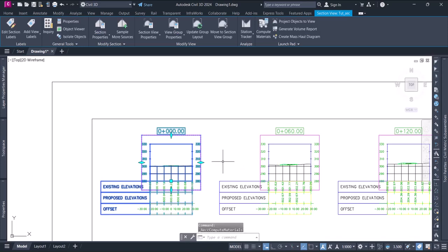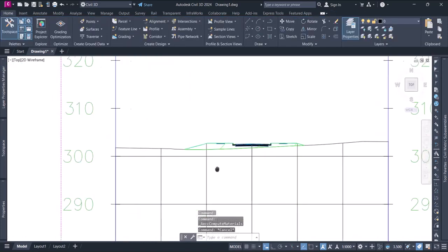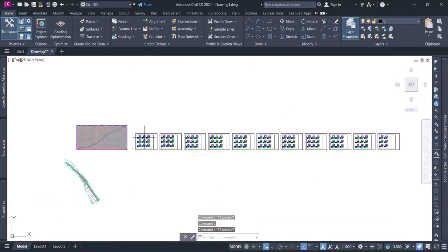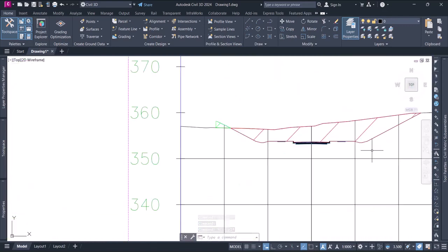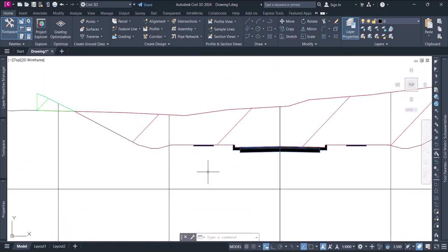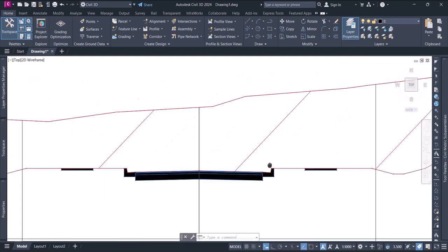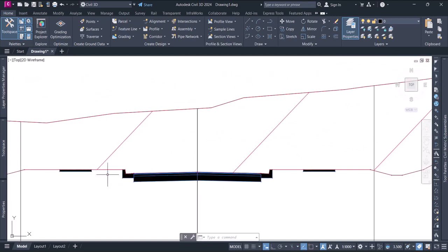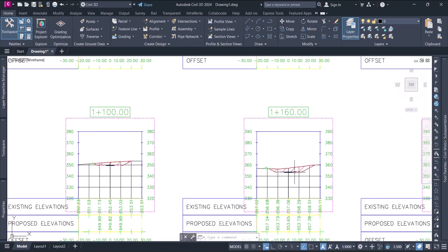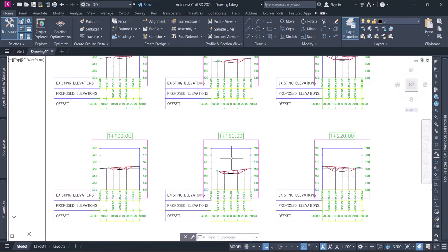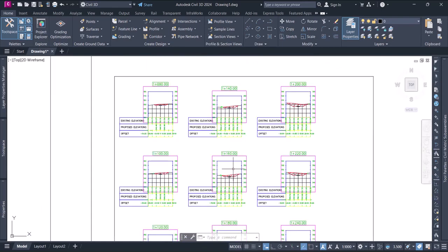Okay, now you will see the hatches appear. This is in fill, and when you have surfaces in cut, the red is marked. The thing I was talking about is, you see, this is actually taking the top surface. So this is cut, but actually we need to cut till the bottom of this one, right? So this is wrong. We will see how to adjust it, but at least you know the basics from this tutorial. My target is to make you familiar with the basics first, step by step.